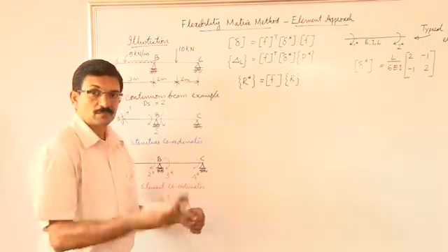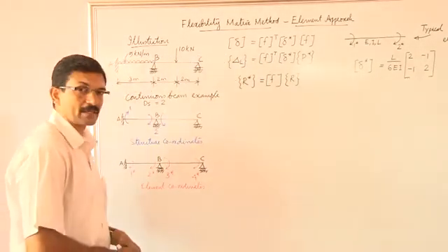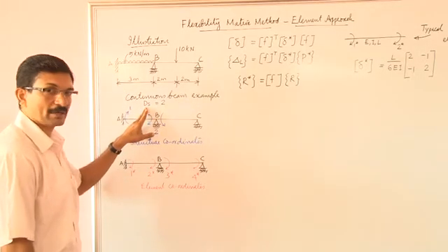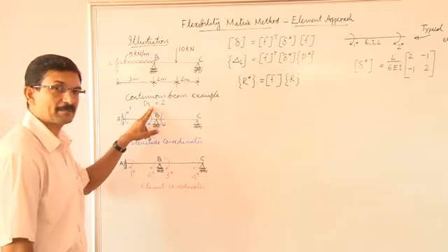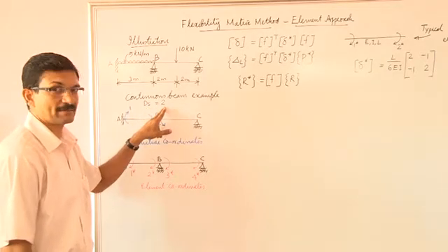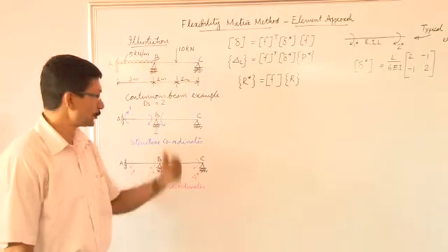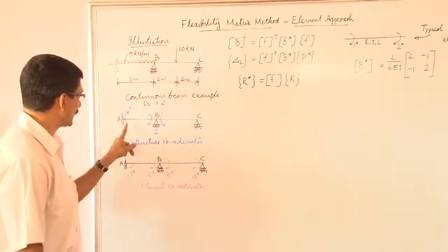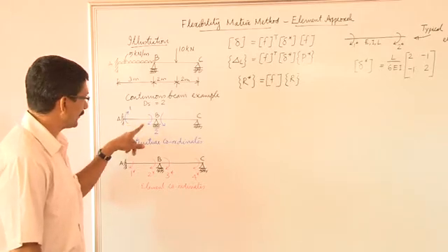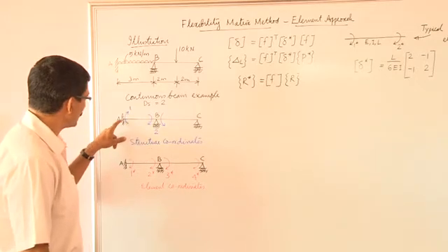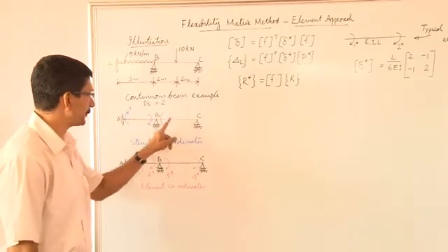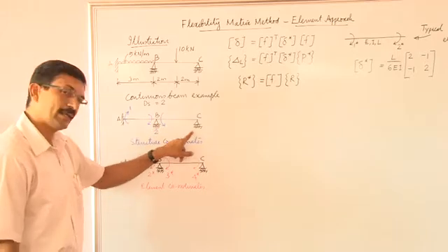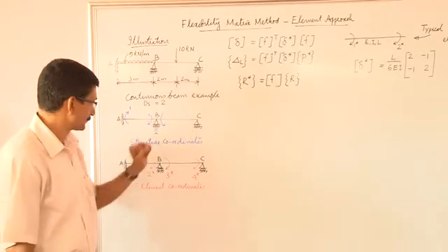Now let us come back to this continuous beam example. First of all, I have found the degree of static indeterminacy of the structure, which is equal to 2, as we saw in this example previously for the structure approach. These are the structure coordinates of this example. We have a moment coordinate over here and a moment coordinate over there. If you remove the moment from here and the moment from there, the structure becomes statically determinate. These two spans then behave like simply supported spans.